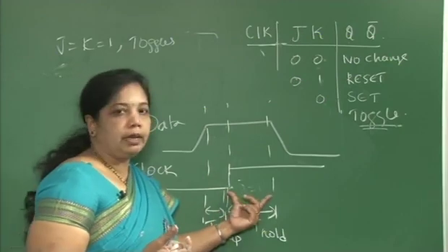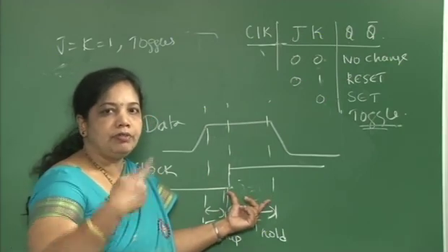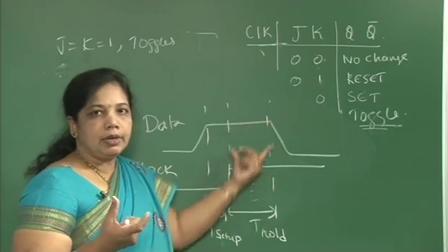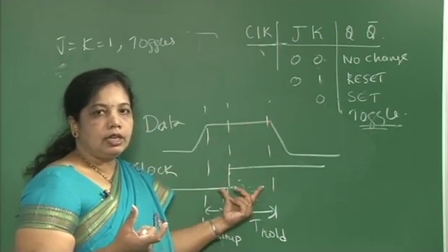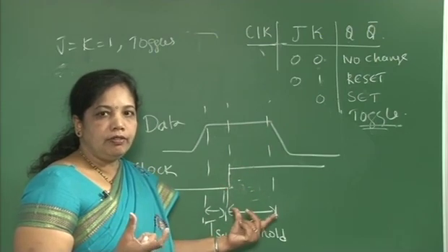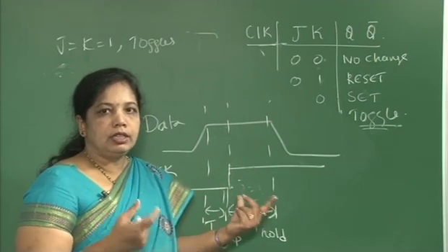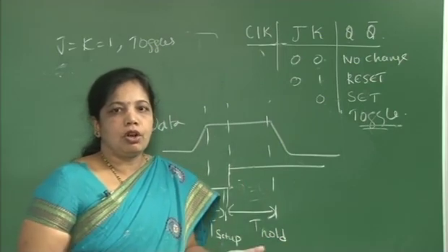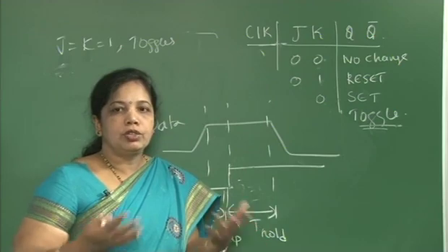So what is hold time? Hold time is the interval after the clock, after this clock, where your data must be held stable. The data has to be held long enough for the interval so that the transistor should switch states. Once the transition is assured, we can allow the data bit to change.